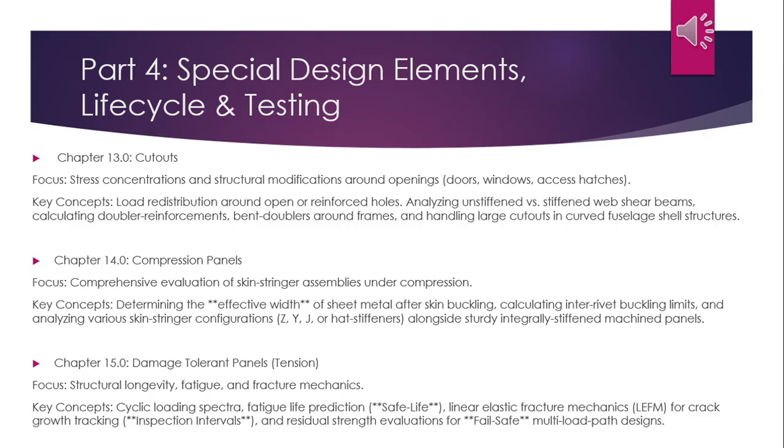The key concepts is cyclic loading spectra, fatigue life prediction, safe life, linear elastic fracture mechanics, LEFM, for crack growth tracking, inspection intervals, and residual strength evaluation for fail-safe multi-load path designs.